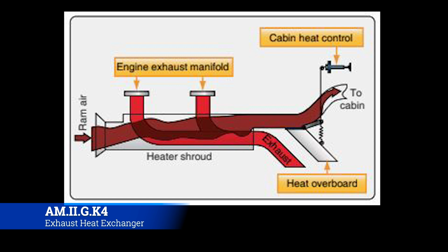And so this is something you want to pay attention to, so that way you can catch it before it kills somebody. And you'll see multiple ADs will come out looking for exhaust cracks. You'll see like any time that this setup is being used, the FAA particularly is going to be very, very, very keen to make sure that people are protected from it, and that's usually done via inspections during the annual inspection.